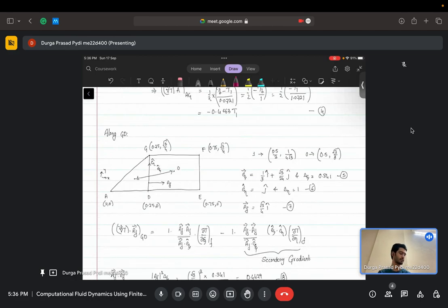So now along GD is where we need to be a little bit focused. So along GD, this is our area vector. Area vector is normal to the face CD, and then E epsilon hat is along the line joining the cell centroids. So this is our E epsilon hat, and then E eta hat is another one. So the angle between these two is essentially not 90. So it is a non-orthogonal mesh. So you know the cell centroid values. So E epsilon hat is along, since you know the coordinates of 1 and 0, you can calculate E epsilon hat, that is essentially 0 minus 1, and then E eta hat will be along the y cap direction, z cap direction. Delta eta and delta epsilon, you can calculate those values.